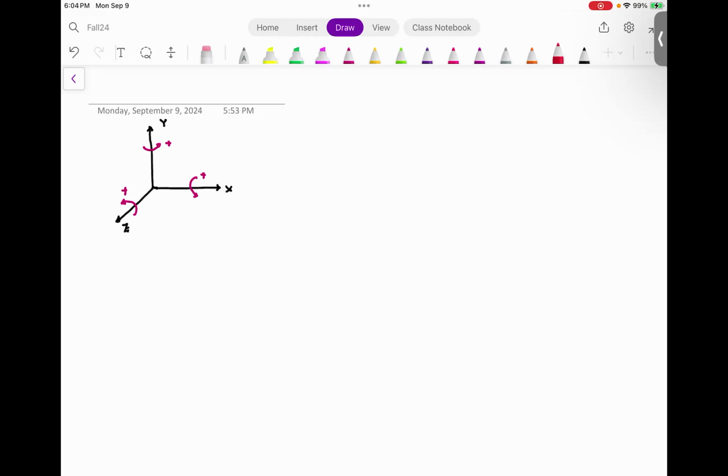This approach is radically different from approaches given in any of the robotics textbooks. So please understand this concept very, very carefully. So what you have is this x, y, and z, and I'm going to rotate this coordinate frame. This is x, I'm going to call this x0. I'm going to call this y0, and we are going to rotate about z0. So z0 and z1, and this frame after rotation is something like this.